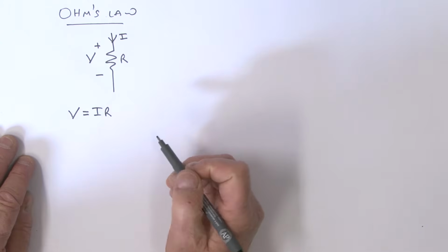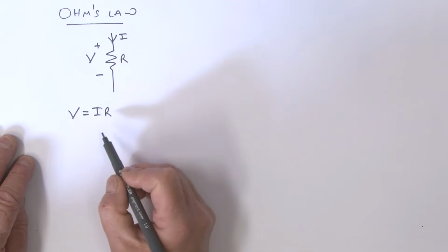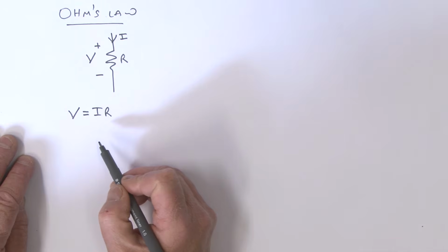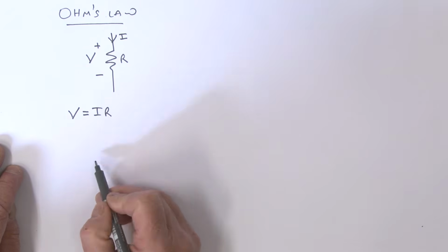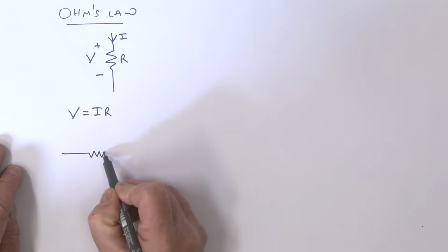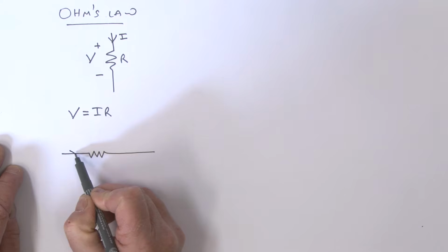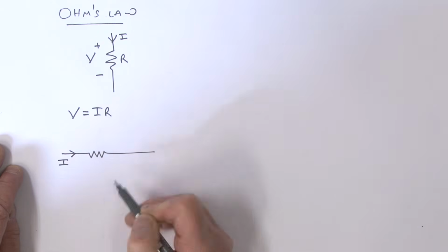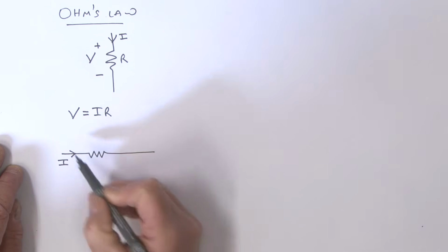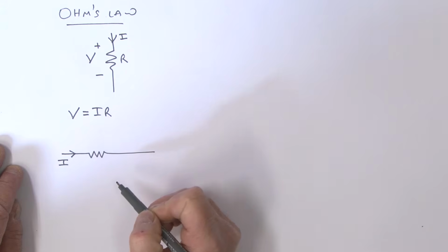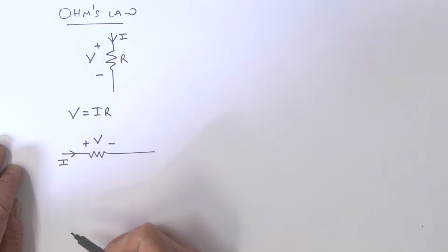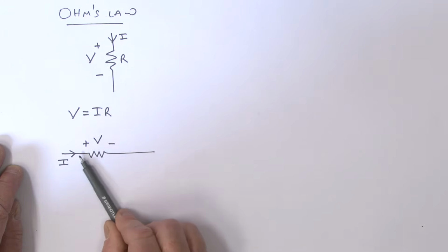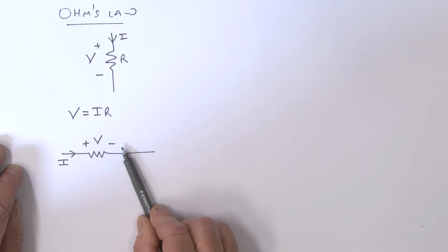All right. Now, look, just a couple of things to think about here, and really this is a bit of a discussion on what I'm calling defined directions. Let's imagine I have a resistor sitting here. And if I define the direction of that current I, to label my voltage to be consistent with that defined direction, I'll label it as plus, minus, and I'm going to call that V. So in other words, this current is flowing from a high to a low.